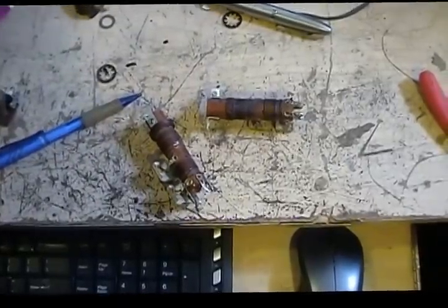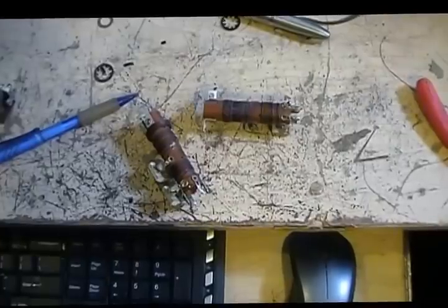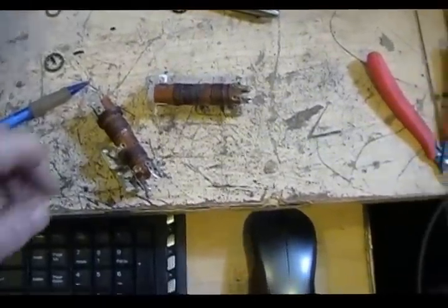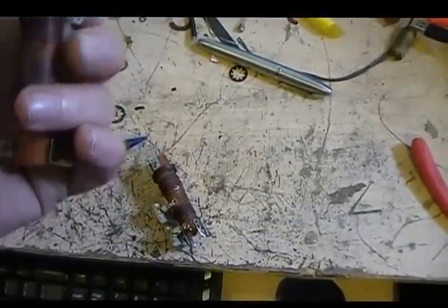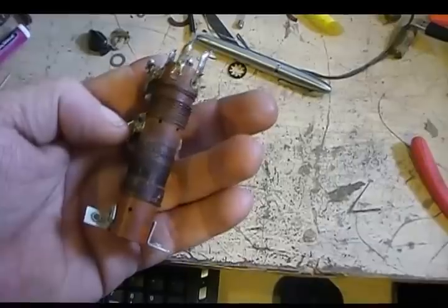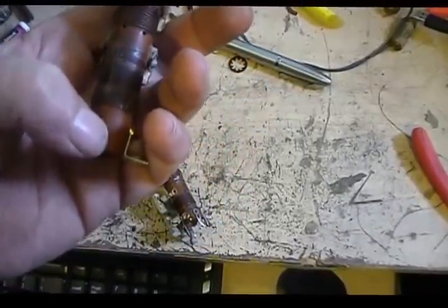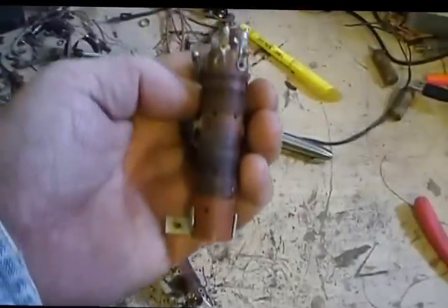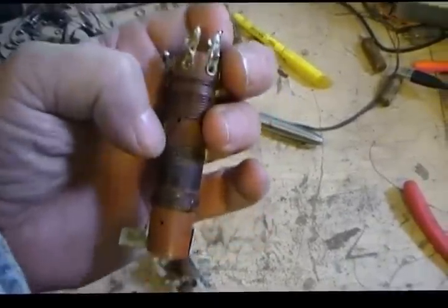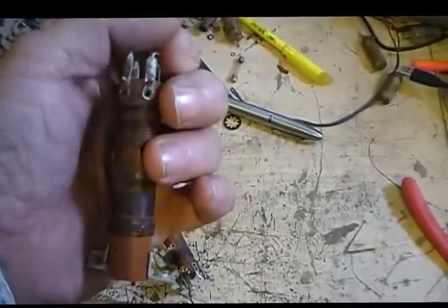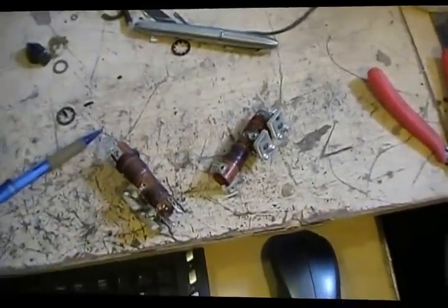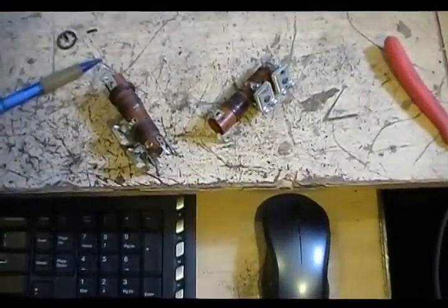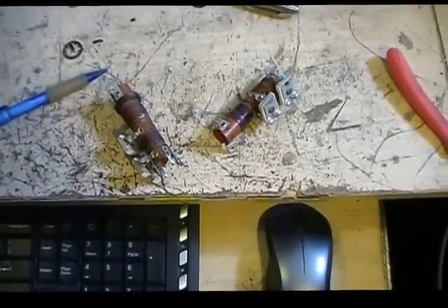If I don't have any real good documentation, as far as the schematic goes, some schematics will actually show the coil. They'll number the connections 1, 2, 3, 4, and whatever, and they'll have something at one side and one end that establishes that it's this side we're looking at, and not this side or that side. We're looking at the coil like this, and this is 1, this is 2, this is 3, and this is 4. But other schematics won't do that. So how do I know? How do you find out where everything hooks?